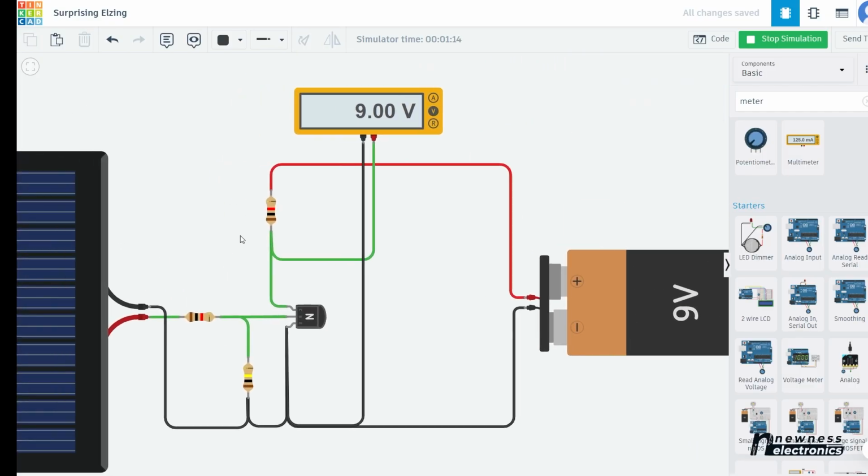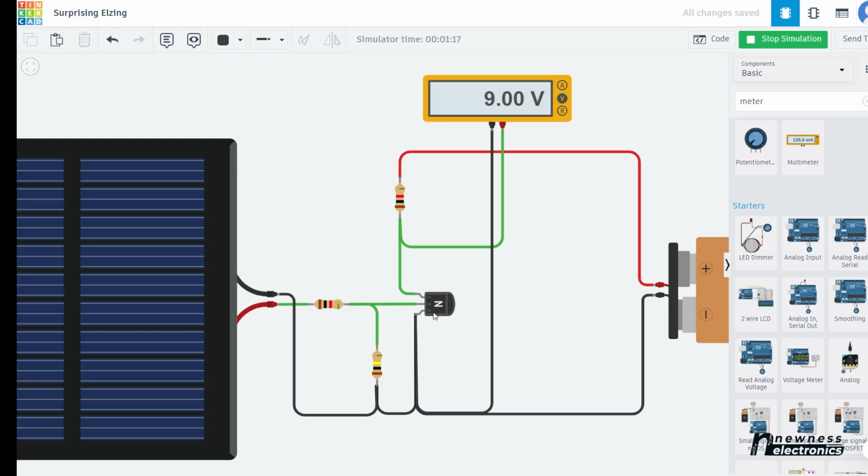Do you see that? So when the transistor is off, the resistance of the transistor to the current path has increased significantly. At this stage, the resistance between the collector and emitter can reach many mega ohms. So technically, current is not flowing to the ground anymore. What am I saying? When the transistor is off, the output voltage is almost equal to the supply voltage. When the transistor is on, the output voltage is almost equal to 0. Do you get? So we can use that characteristic to create something called an inversion circuit.